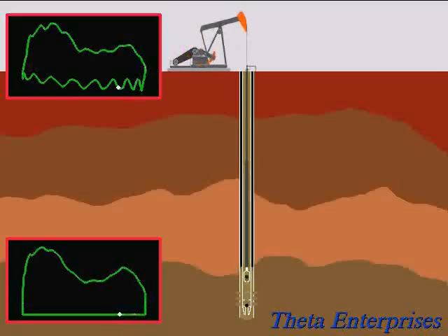And one of the primary reasons for that is because the rod string doesn't stretch. Well, it stretches a little bit, but not enough to absorb the shock of picking up the fluid load. So you see a large dynamic load on the plunger